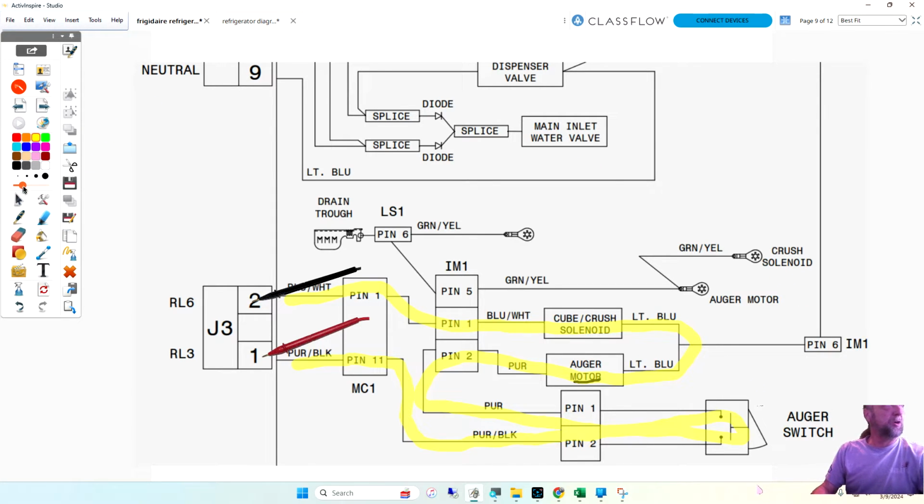But we could reduce that. Anybody get any idea how I could reduce it? I was thinking of doing a voltage test. Okay, so where would you do your voltage test? That's a good test. So if I do a voltage test on J3, and I can isolate the board, I know it's not a board, then it has to be any of the components on that path.